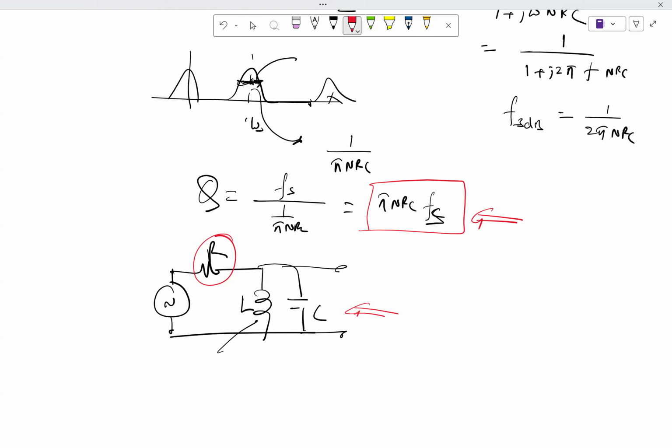We cannot go very high with the frequency, yes, that's a problem. His point is that these RLC networks are not dependent on a clock, so you do not have to supply sharp, high frequency clocks. The problem with these N-path networks is that they depend on some sort of clock.